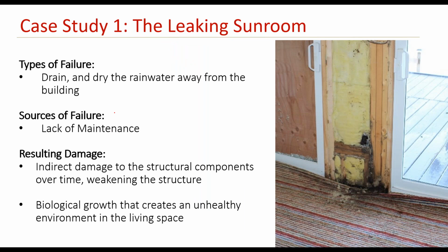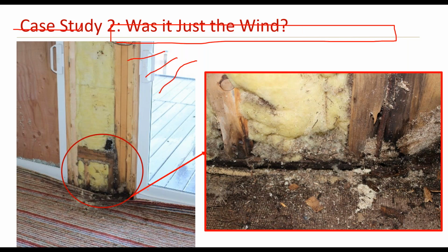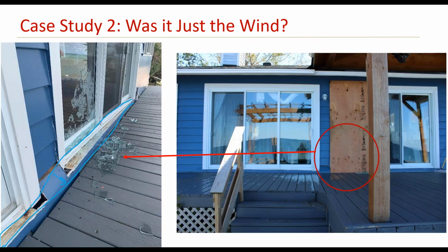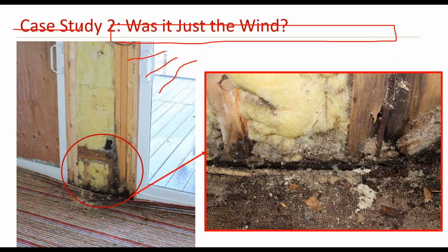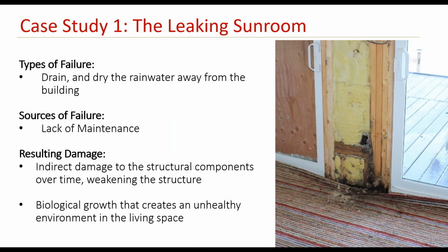The reasons for the failure here were, first of all, lack of maintenance, and we did not see proper sealants around the windows. And also, lack of maintenance and cleaning of these sliding doors would block the weep holes and prevent proper drainage of water, and as such it would accumulate at the stud post location.